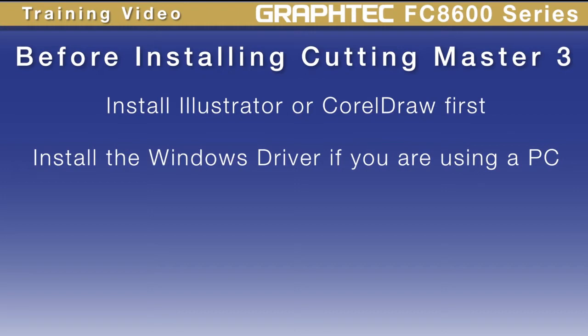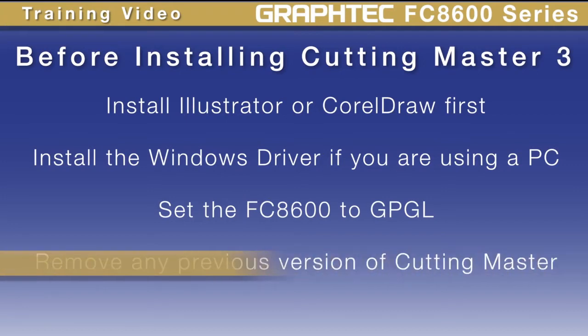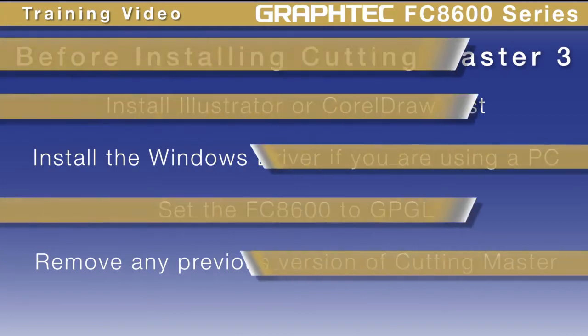Since Cutting Master 3 outputs to Graphtec's cutter language, known as GPGL, the cutter will need to be set to GPGL mode. This was covered in the installation and setup lesson of this video. If you're not sure how to do this, review that lesson or look in your manual. Finally, prior to installing Cutting Master 3, remove any previous versions of Cutting Master 2 or Cutting Master 3.